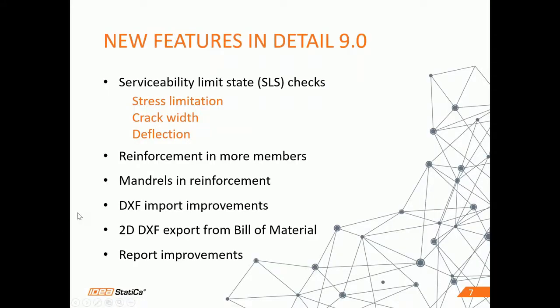So what is coming in Idea Statica Detail version 9? The big improvement is the implementation of the serviceability limit state checks. So we now have stress limitation, crack width, and deflection checks available.